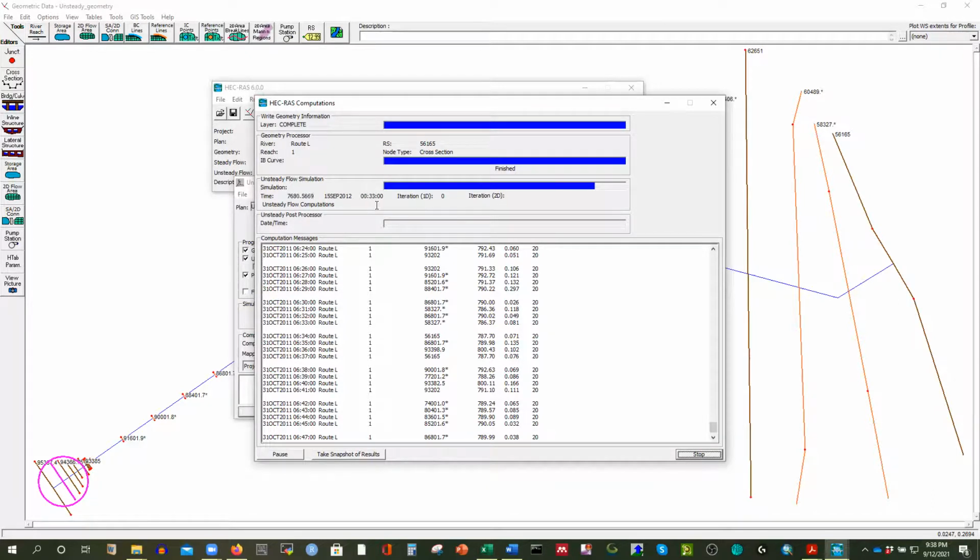Otherwise, when we add our sediment data, the model may blow up, and there will be different issues. So that's why we have to test with different time steps, because it is solving the differential equation, for unsteady flow or steady flow, whatever.